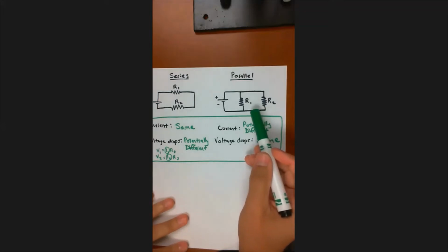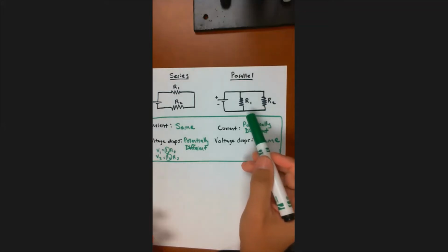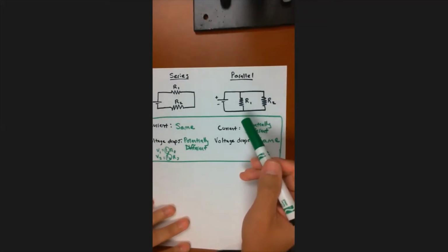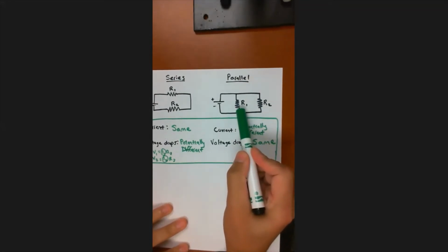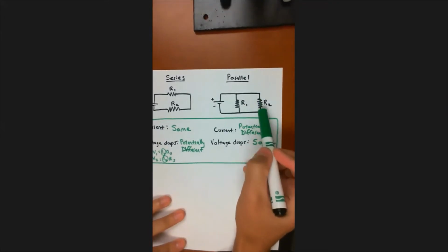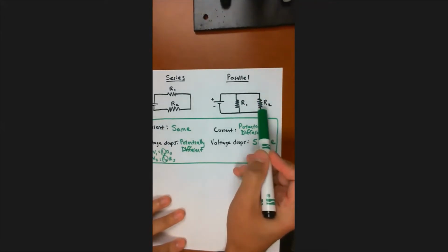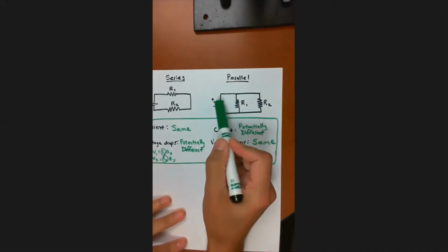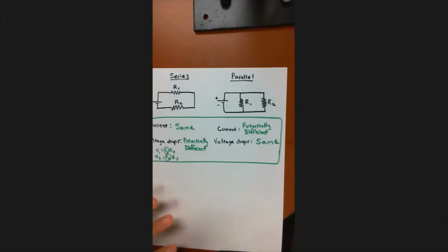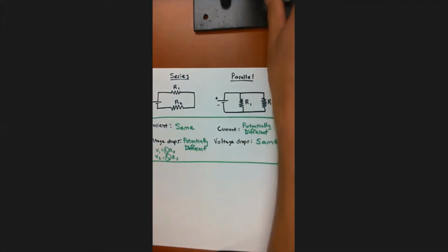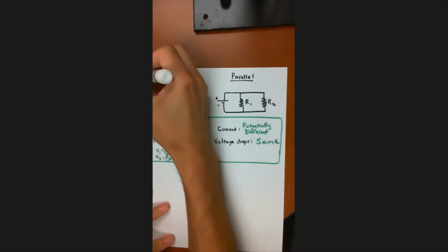For example, if through some other means I was able to calculate the voltage drop V1, then automatically I would know the value of V2. And I would also know the value of the voltage source if I didn't know that yet. So it just comes in really handy if you just know these different concepts. So that's concept number 1 for today.